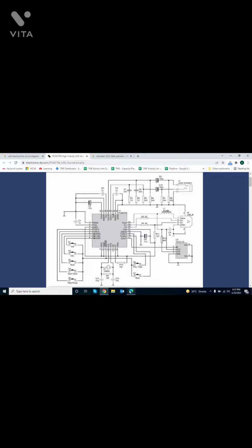And pins number 13 and 12 are connected as a 12 MHz crystal oscillator with a 1 megaohm resistor in parallel, and two 27 picofarad capacitors to ground, in order to make oscillation. Thus this acts like a resonance circuit.